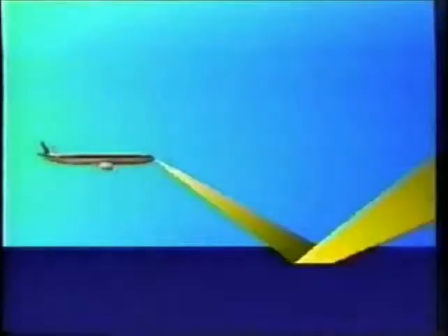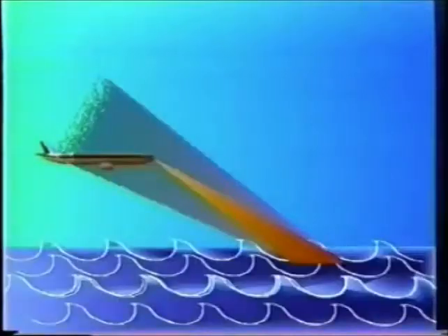When attempting to map sea returns, be aware that calm water provides a very low radar reflection. It acts like a mirror and reflects the pulses forward and away from the receiver. The same is true when viewing the sea from a direction parallel to the waves. A much stronger reflection can be observed when viewing the sea in the up and downwind directions, the upwind being the strongest.